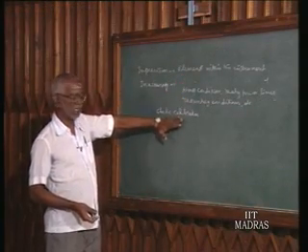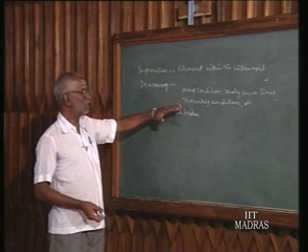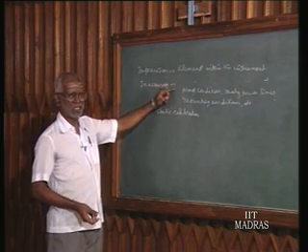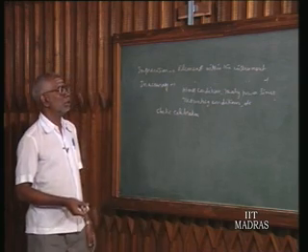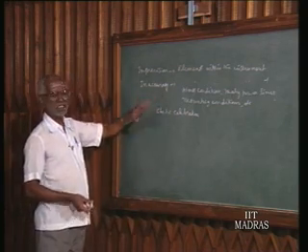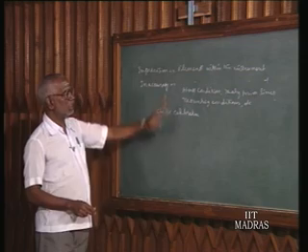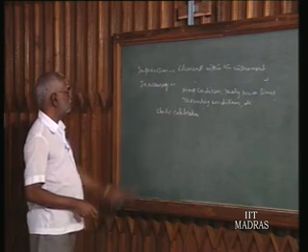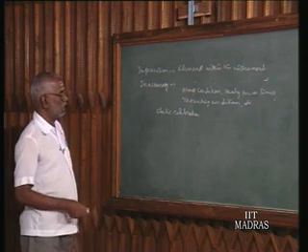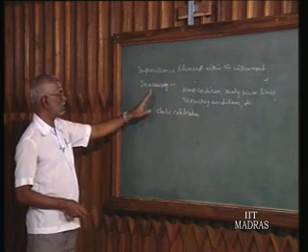So by the process of static calibration, what we normally achieve is that the higher value of inaccuracy is brought down to the value of imprecision, and reducing below imprecision is not possible. That is, it is decided by the elements you have selected at the time of design and manufacture. So these are the sources, and sometimes you find inaccuracy is given